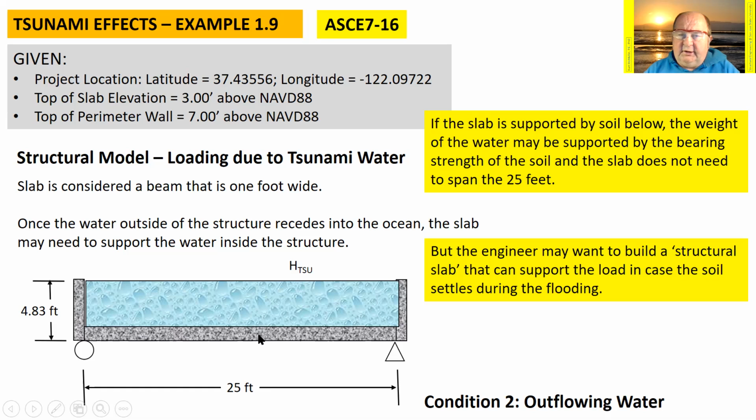But we're considering this as a structural slab with supports at the two ends. Perhaps one reason to do this, even if it's on the ground, is that we expect the soil may be settling away or may not have very much strength to begin with.